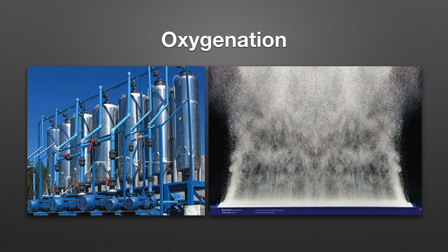Oxygenation, where you're adding pure oxygen to the water. There are several different ways to do that. Typically, liquid oxygen is used, or oxygen generators, then supplied through very fine pore diffusers, really small bubbles.